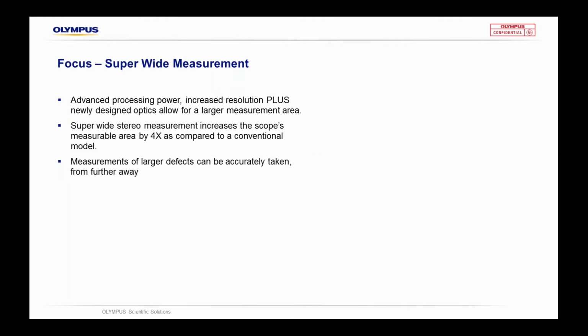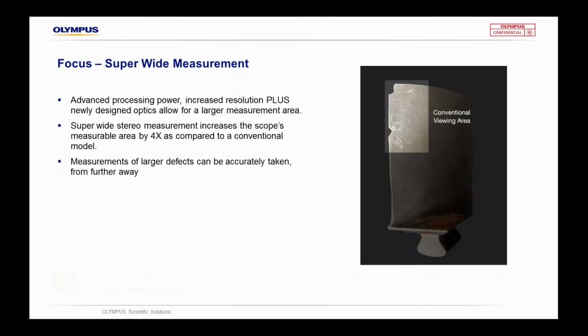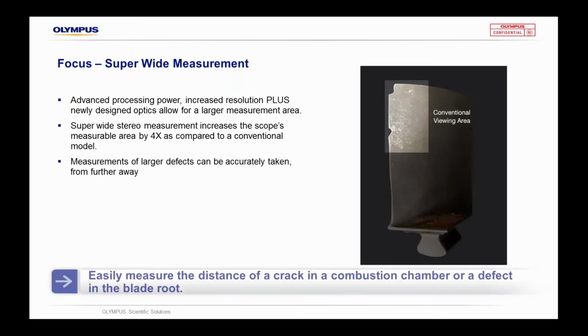One of the important things is sometimes when you do find the defect, specifically if it's inside some rotating machinery, specifically if we're looking at a blade within a turbine, as we can see on the screen here, it's important to actually quantify that and carry out a measurement and find out how big that defect is. Is it within tolerances? Is it in line with what is acceptable within the maintenance manual? Do we just want to track this to see how it is changing over a period of time?